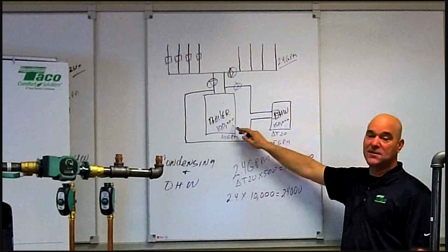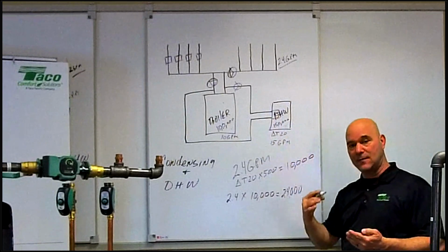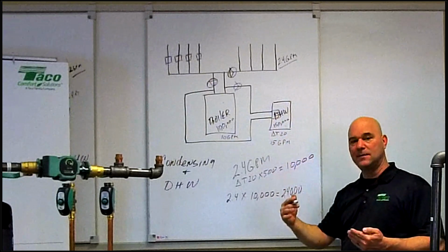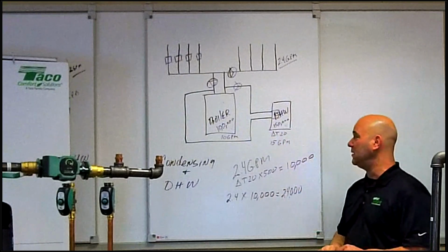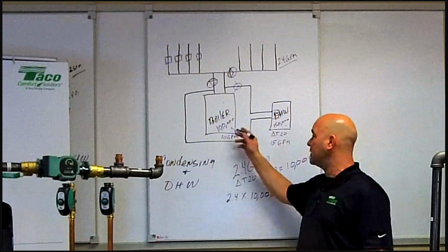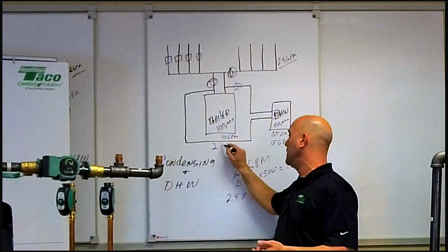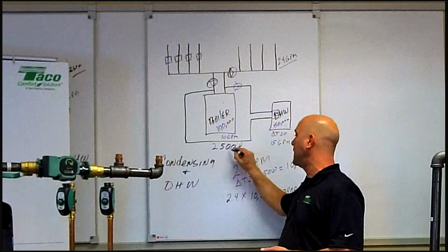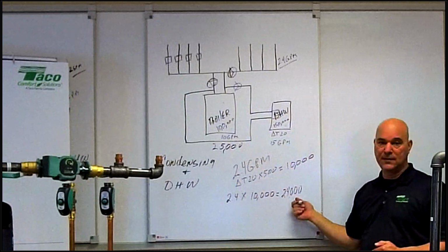So if I were to upsize this boiler to get to that 150, I need to know the turn down rate. What's the bottom of that boiler's capability? So if it's 100,000 BTU, I may only be able to turn down, who knows, if it's a 3-to-1, whatever, but I want to get somewhere down in that 25,000 BTU range with that boiler because this is my smallest load.